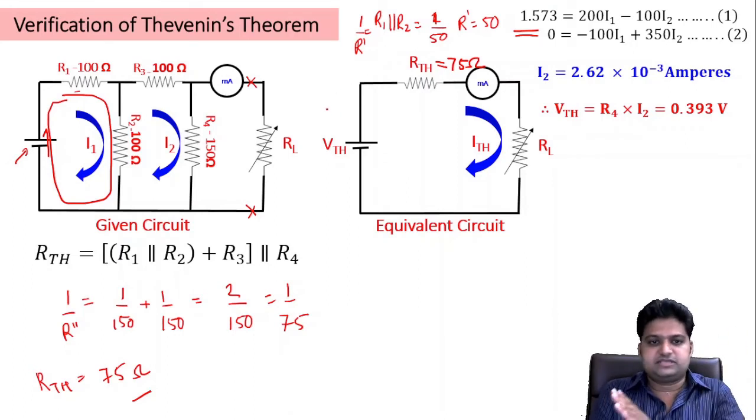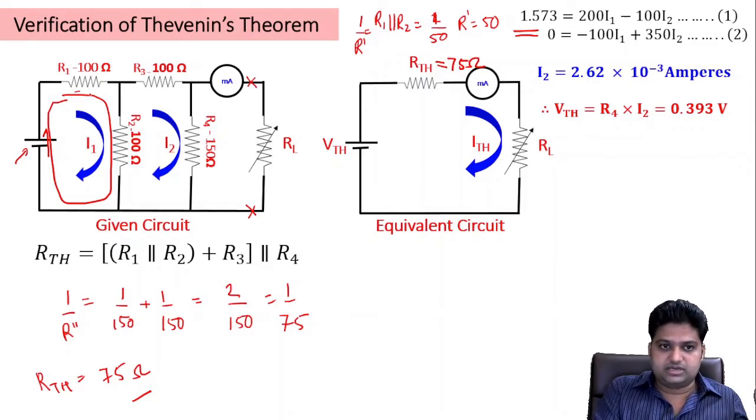Now if you have to solve for the next equation, in this circuit we do not have any potential, so it is equal to 0. So 0 is equal to negative of current I1, that is this 100 ohms, plus 100 plus 100 plus 150, that is 350 ohms I2. The I2 current will deal with these 3 resistances over here, and from that side only 100 ohms. Is that fine? So these are the two linear equations that we have.